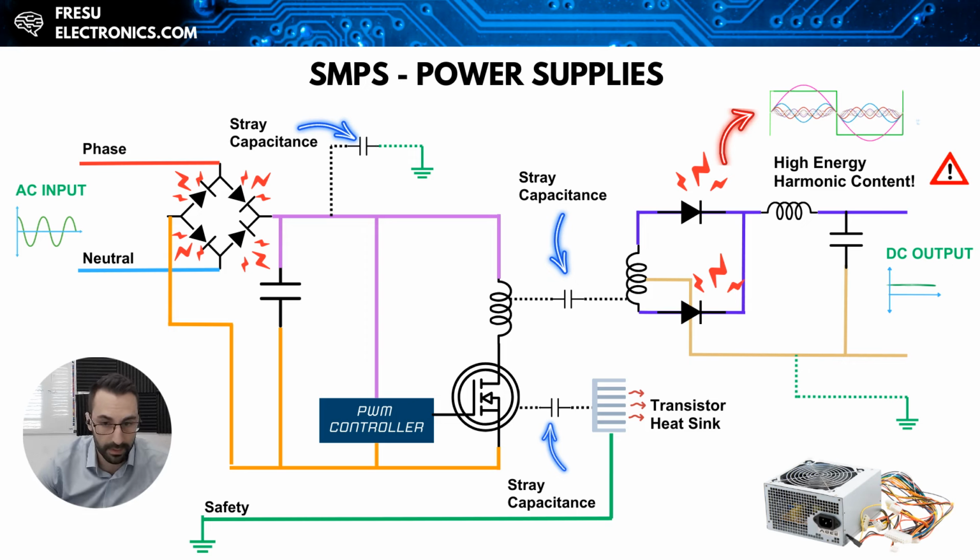But this does not mean that the rectifier on the primary side of the power supply should be left without consideration or taken for granted, because of course we will have to take them into account as well. So these differential currents produced during this reverse transition time can find ways to couple back to the primary side of the transformer and ultimately to the power distribution network. And it's important to know that this effect is also common in switching transistors, and in particular for us, these effects need to be taken into consideration for the switching transistors of the power supply.